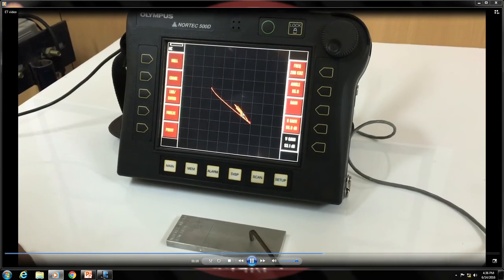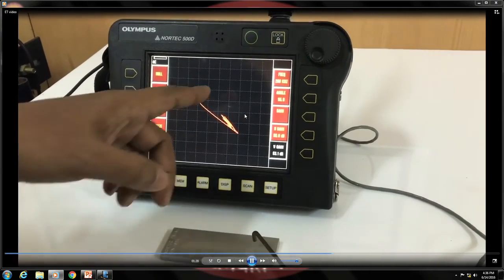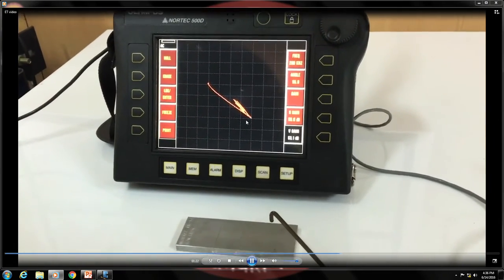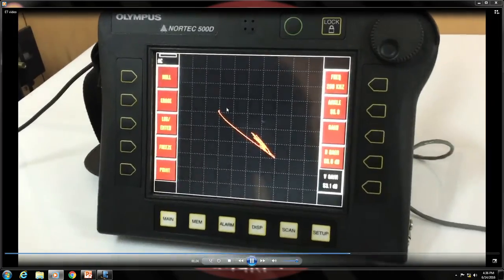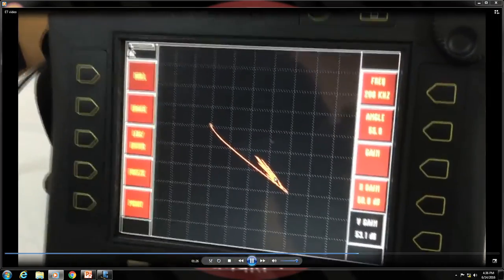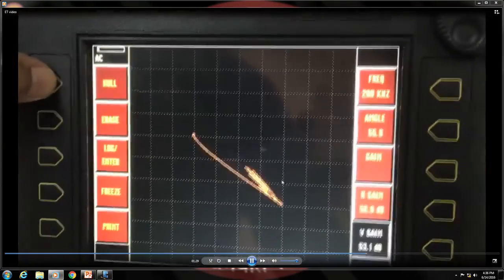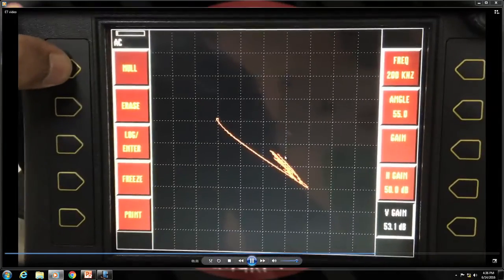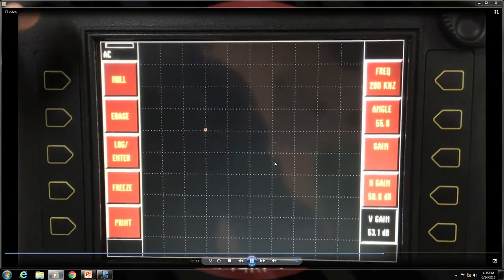Okay. So, this is how the moment the probe moves over a defect, you could immediately see a spike above the lift off curve like this, okay, where the arrow is. So, this is the crack signal.